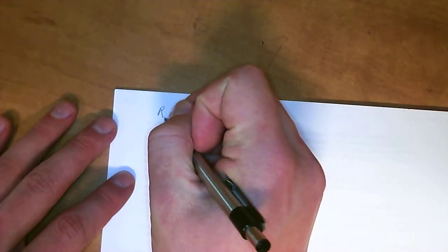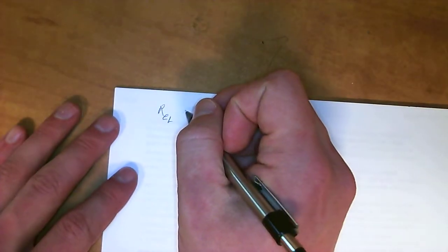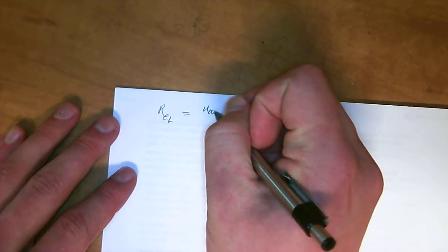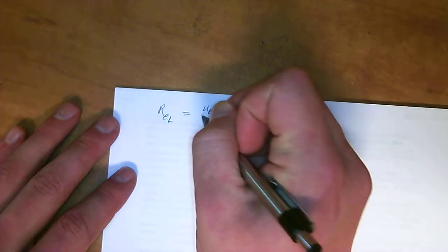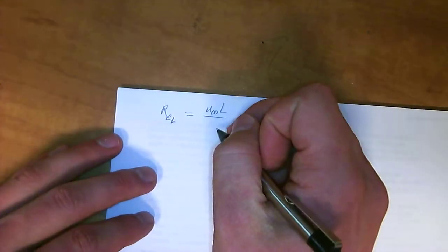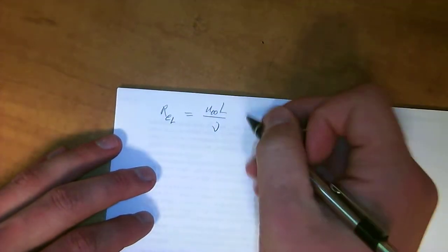Okay, so now I'm just going to jump right into this analysis. Pause the video a second ago and get that drawing because I'm probably not going to show it again. The first thing you have to do when you solve one of these problems of air flowing over something is figure out whether it's laminar flow or turbulent flow. So you need to figure out the Reynolds number for the length of the piece that you're working with. You've got the velocity of infinity, the length of the total piece of plate or substrate and chip, and then you've got mu, which is the viscosity.